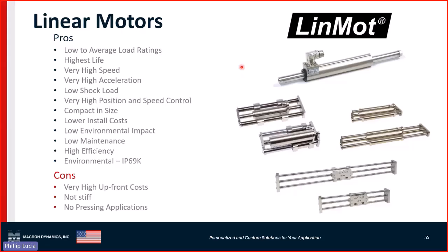They have the highest life of any technology, super high speed, super high acceleration, low shock load, meaning that they can't maintain their position very well if you give it a big shock, because there's no mechanical advantage to keep metal to metal contact to kind of hold that thing stiff. They do great with position and speed control. They're compact. They're pretty easy to install. The lowest environmental impact, because there's nothing there that has to be maintained. There's no oil or there's nothing like that inside.